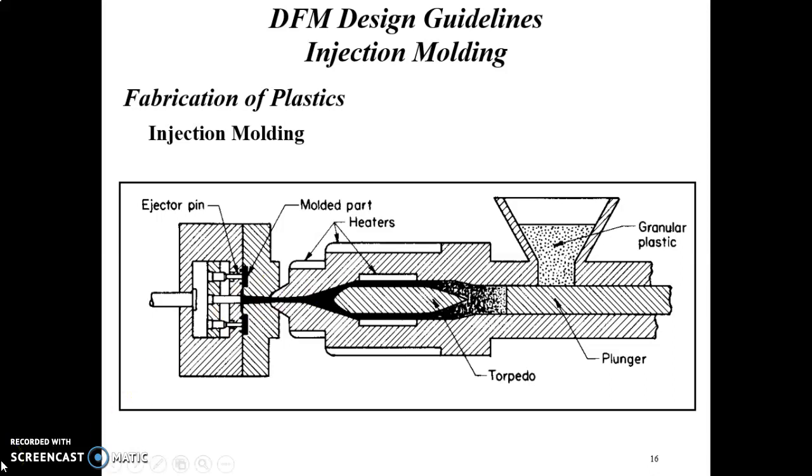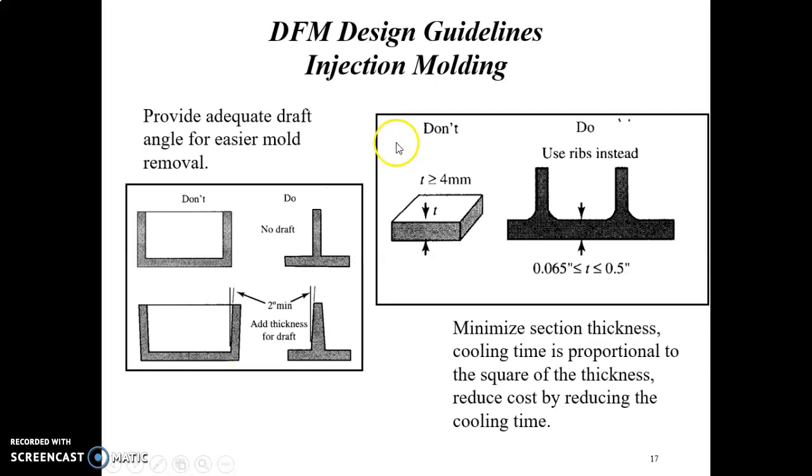Okay, we look at DFM, Design for Manufacturing design guideline, which is first about injection molding, the fabrication of plastic by using the injection molding. What we should consider first: provide adequate draft angle for easier mold removal.